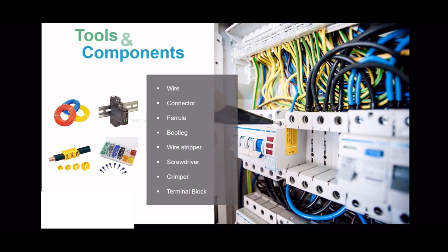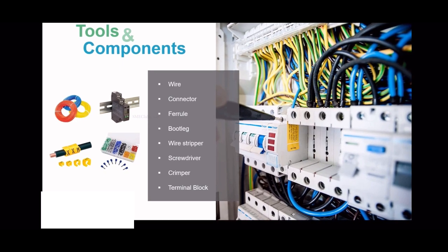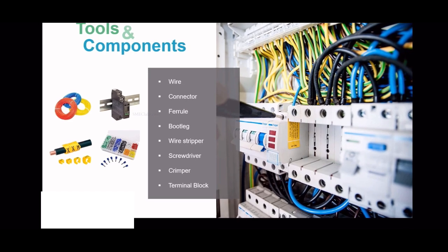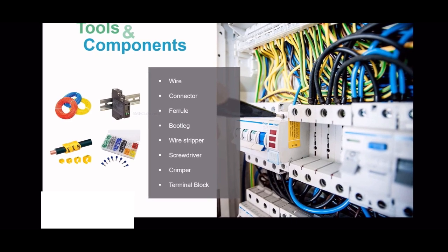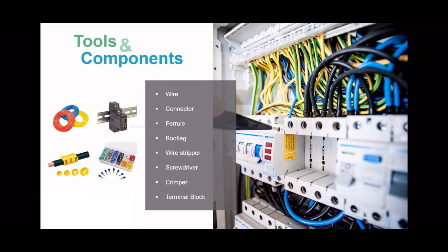For the load supply or the 3-phase supply, there are already standards, that means a wiring color code also. Okay, for the wiring color code, according to the Indian standards, for the phase you can use the red color, for the neutral you can use the black color, and for the earth you can use green. Then there is the control wiring and the DC wiring too. For DC wiring we have to use the yellow or blue color wire.